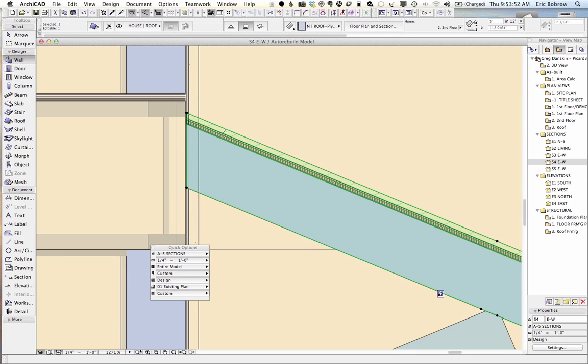So the asphalt shingles obviously should have a lower priority than the outside of the building sheathing, the wall sheathing. The wall sheathing, and the asphalt shingles. I would imagine you'd want them to stop before the stucco. You do the stucco first. Right. All right. Now, one of the things is that ArchiCAD will not do an intersection between these elements just because they happen to bump into each other.